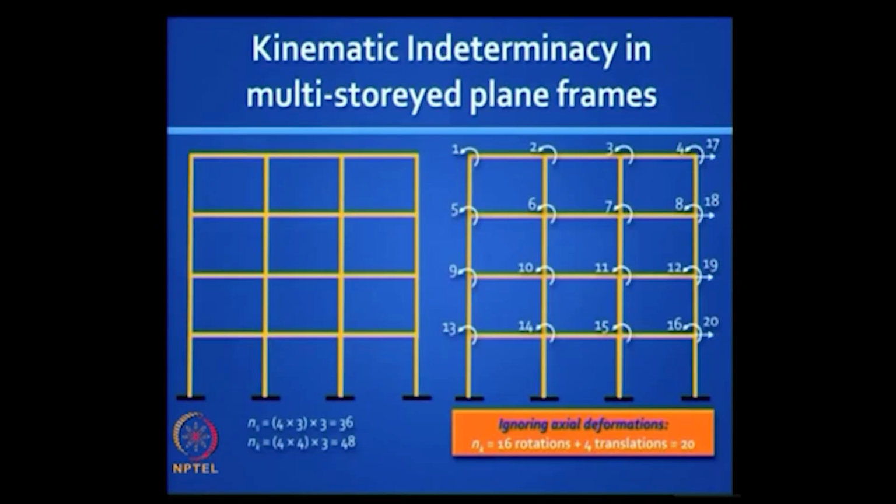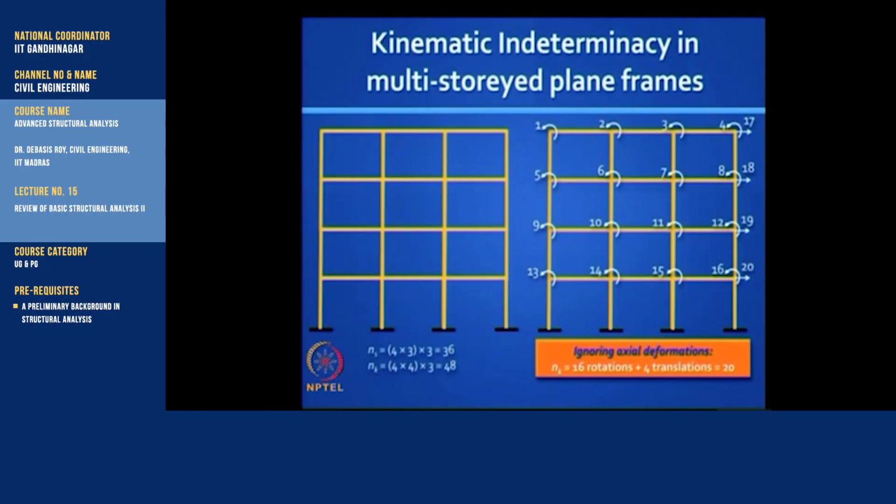And there are serviceability limitations in a tall building. The maximum drift in the building should be limited, okay. Usually it is height by 500 under lateral loads, okay. So can you analyze a frame like this? Exact solution? Yes, that is the idea. We want to be able to handle any structure, any skeletal structure of any shape subject to any loading, including indirect loading, okay. That is the objective of structural analysis.